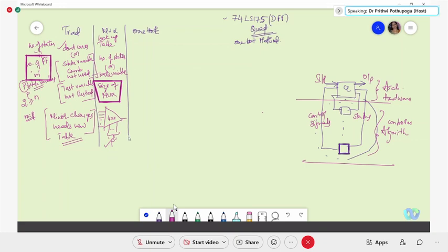Not only that, we have one more method. These two are competitors now. Actually, mux and one hot are the most prominently used, but the hitch with one hot is that here we are not taking the number of state variables, rather directly the number of flip-flops will be equal to the number of states. Here the cost of the design will be a little bit more compared to these two methods, because the flip-flops are directly related to your number of states.